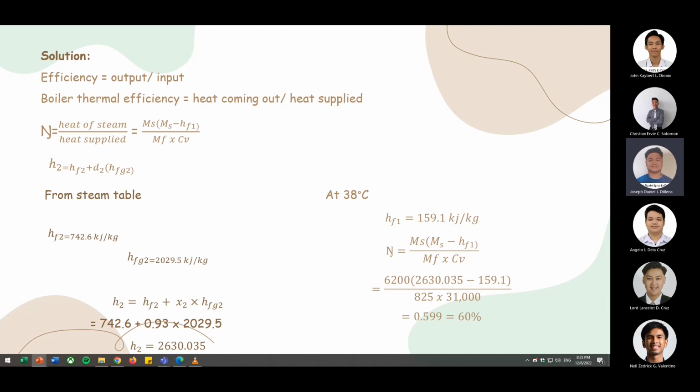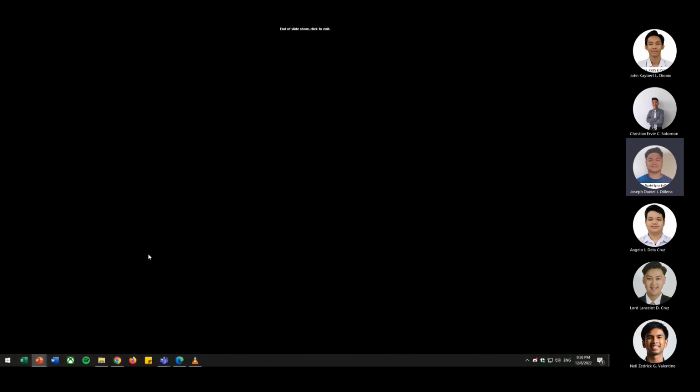And using our equation for efficiency, 6,200 times (2,630.035 minus 151.1) over 825 times 31,000, we will get 0.599, or it is equal to 60% efficiency. So thank you for listening to our presentation, and that's all. Thank you.